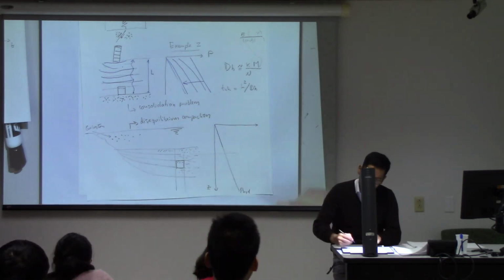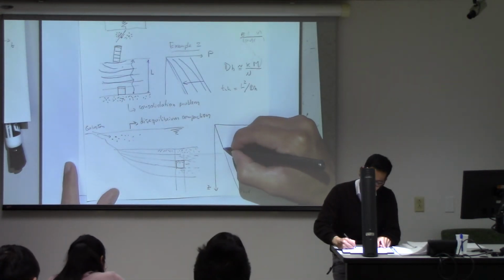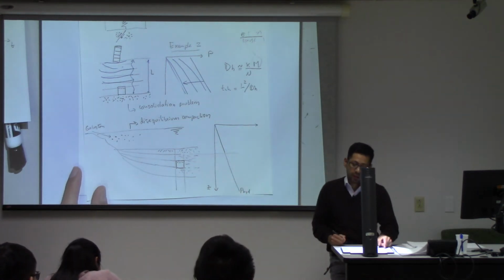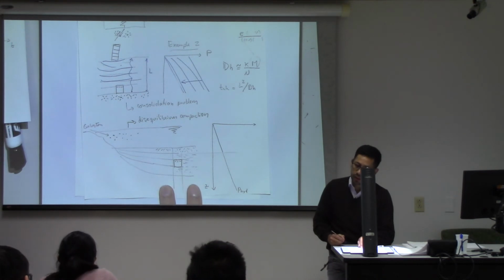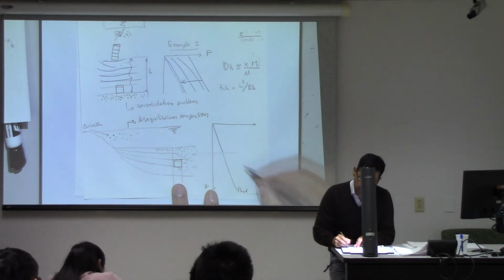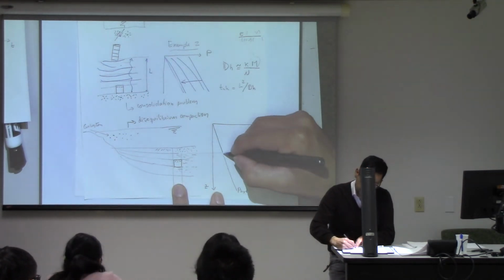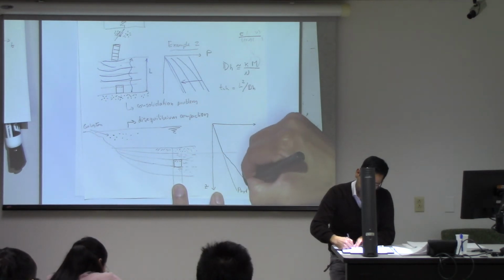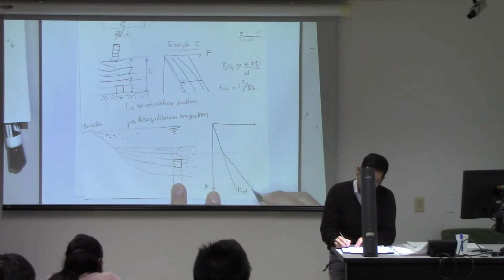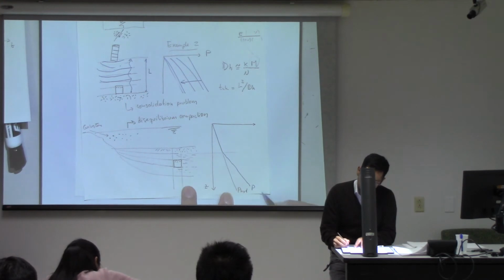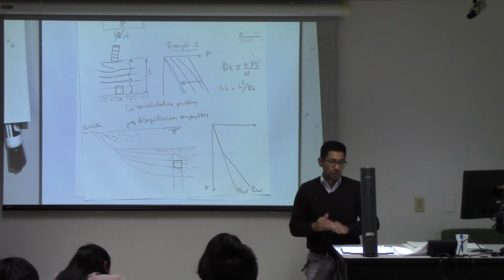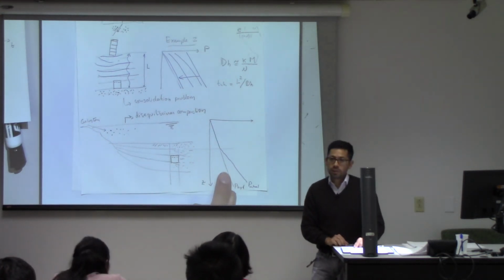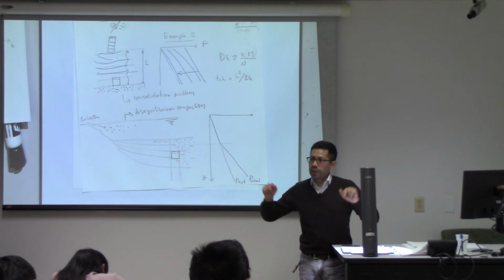You will see that the sandy part, because it has a high permeability, will be mostly a hydrostatic pore pressure. But as soon as you get into the shale part, the pore pressure is not going to be hydrostatic, but it's going to be a value which is higher than the hydrostatic pore pressure.